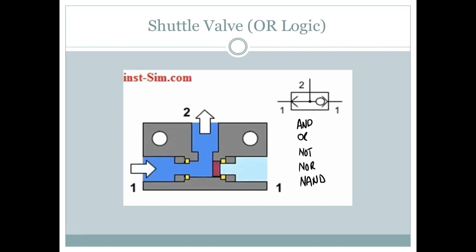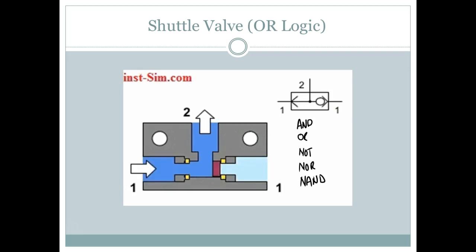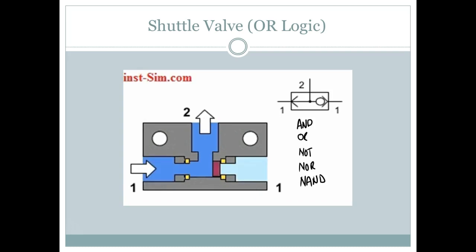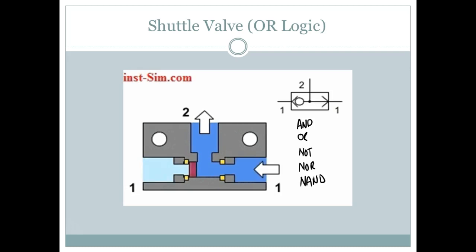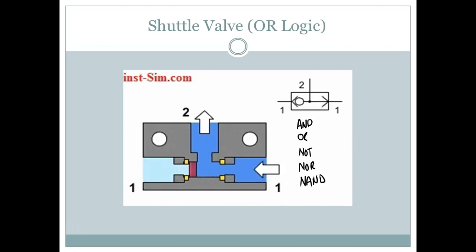So as long as I've got my hand on this button right here, that other operator can beat on that sucker from now to doomsday. All he's doing is making the other port true, but when he goes false, 2 stays true, right? You understand? So we're saying, okay, I've got 1 or 2 could make the press go up or go down, but the other one's not true, right? You understand that? Yes or no?